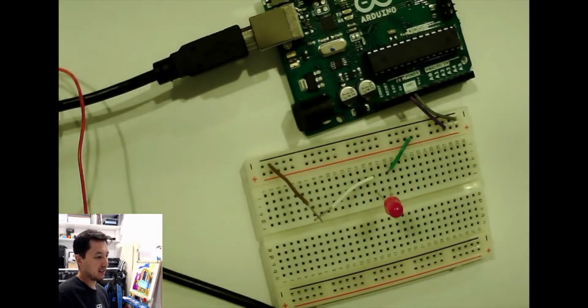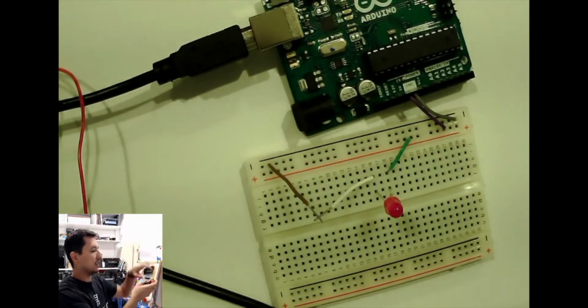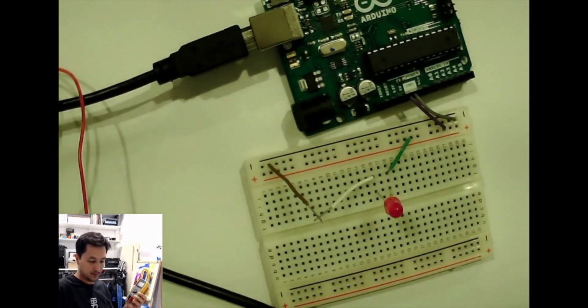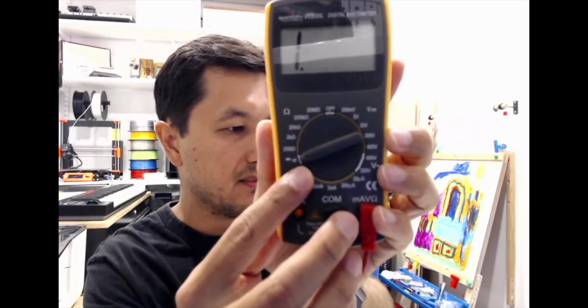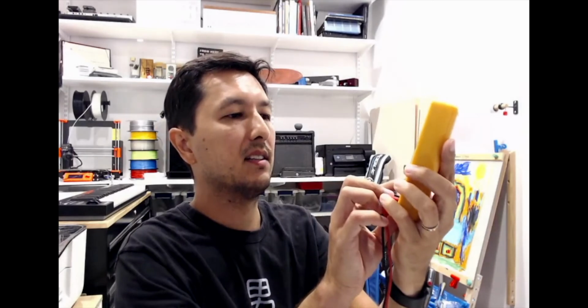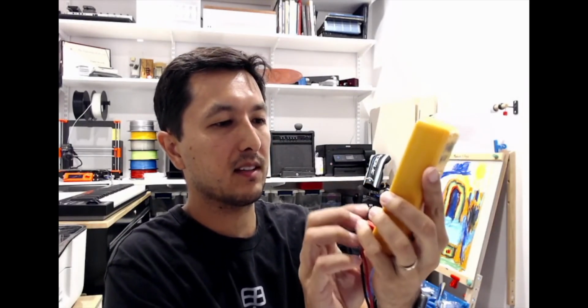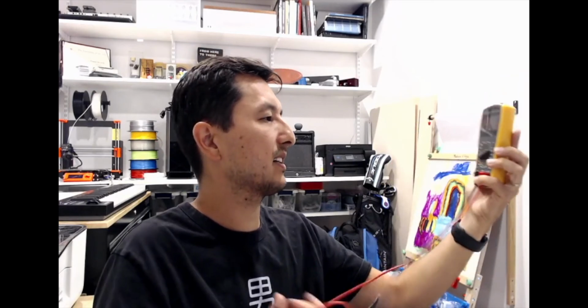If you have a digital multimeter, then you could use that to test conductivity. If you turn it to the connectivity option, which looks like a little LED diode and a speaker kind of thing, or mine looks like a Wi-Fi connection icon, and you touch these together, it should make a sound. Then you can go around your house and touch different things that are metal and seem conductive.